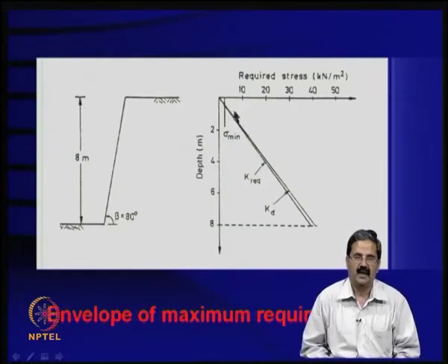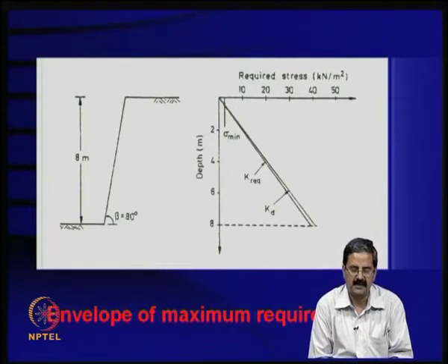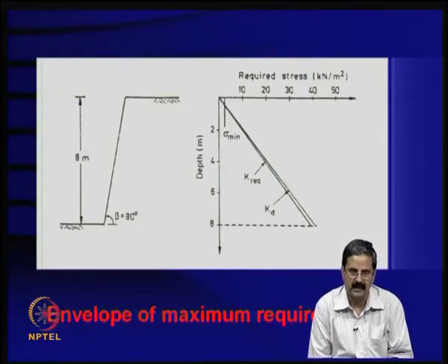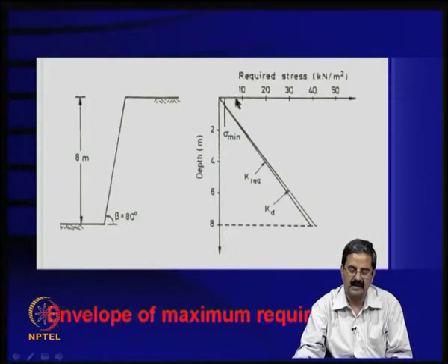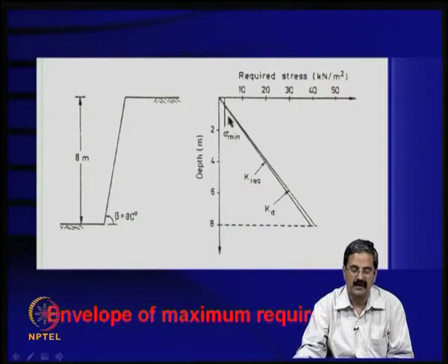If you remember, I showed in the compaction chapter the amount of pre-stress that the materials have. For example, in the case of clays, there is a lot of pre-stress, but in the case of sands it could be lower. So, that pre-stress value one can get from here, and maybe make some correction and then use it here, if you are using compaction. If you are not compacting, it is fine, you need some minimum stress because of the bond considerations. So, this is K required and K design, and then the minimum stress values.